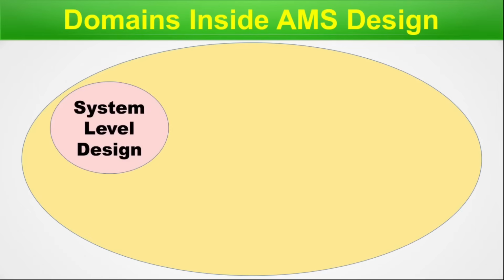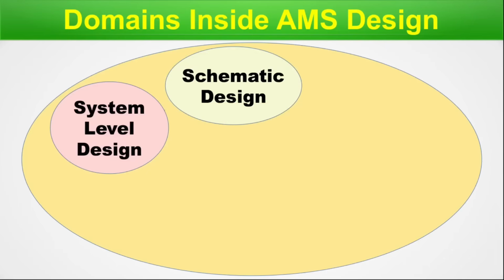In AMS, we start with a little bit different approach. We go either top down or bottom up approach. In either approach, we design the blocks with system level modeling with C, C++, Simulink or System Verilog. All of these skill sets are needed to work at this particular level. Next comes the schematic design for the analog blocks. I have already mentioned this in detail in the last slide of this particular episode. Here we use tools like Virtuoso or Custom Compiler.